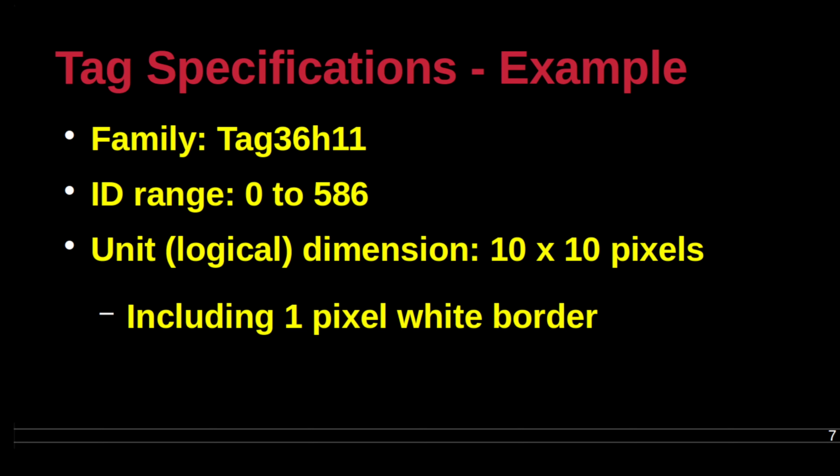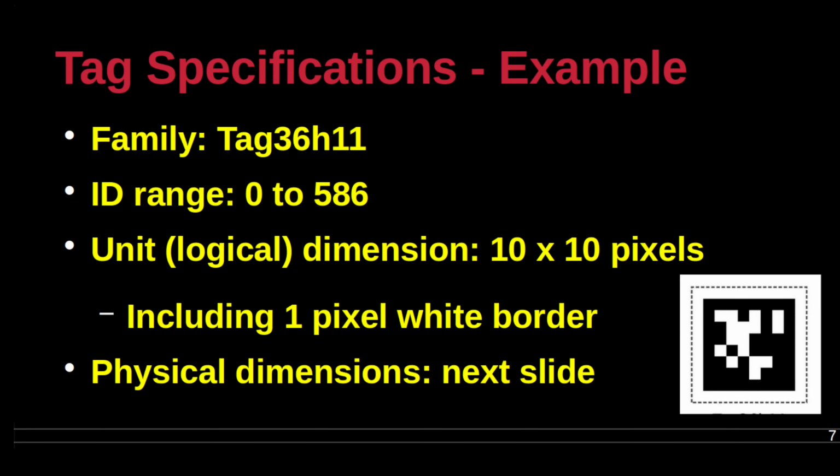This AprilTag family uses 36 bits for encoding with 11 bits for Hamming correction. It has a low false positive rate, which accounts for its popularity, especially when motion is present. There is a simple empirical formula to estimate the farthest distance at which this family of tags at a particular printed size can be detected with known camera lens properties such as focal length and resolution.